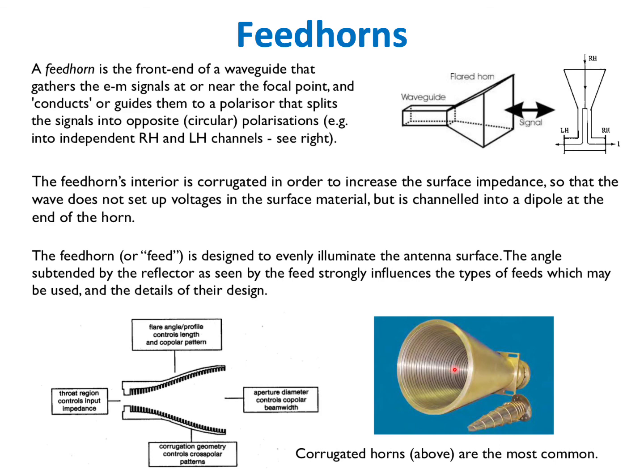That is the size of the focal disk, because we're at long wavelengths, so the focus isn't a point, it's a small circle. The opening of this feed horn then matches that small circle. But then you need to funnel all that radiation down into a smaller point to get it into your receiver, because you don't want to build your receiver to be enormous. You'd like to focus all that down to a reasonable size. Of course you want the feed horn to be round to match the Airy disk, but also because you want it to illuminate the surface of the dish as well as you can. So the dish is round, so you make your feed horn round.